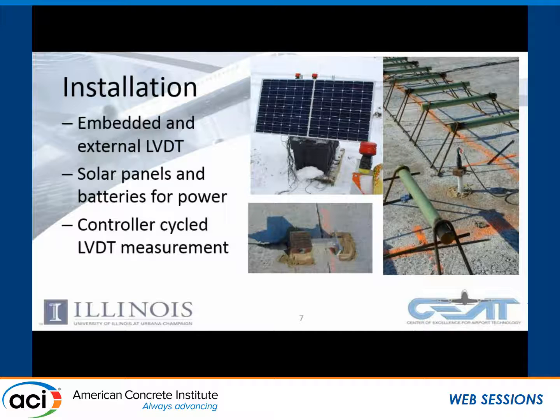And then for the data loggers themselves, like I said, we had to get a little bit creative, and we came up with this solar panel system to run our Campbell Scientific data logger. This was a little bit interesting. We had to become some electrical engineers for a little while to understand how we actually maintain power. We went with deep cycle batteries and monitored the voltage in the batteries. It was an interesting challenge, and what we ended up having to do is cycle the LVDT system, which was independent from the RH and temperature system. The RH and temperature system takes very little to no power, but the LVDTs are quite power hungry.